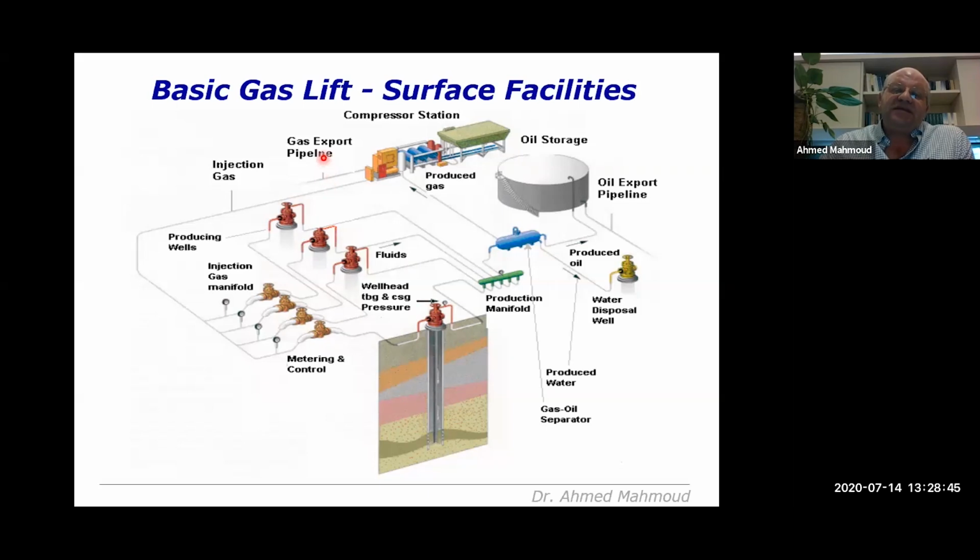First of all, you know that this is the export gas, and the export gas will typically be the good gas, the expensive gas, the gas everybody wants to buy, the gas that can be liquefied. Okay, and the gas which is not sellable is the gas with heavy components, the low quality gas. This gas I can use to recycle throughout my field, inject it within the annulus, okay, and I use it within the gas lift mechanism or system to lift oil, and the cycle keeps on going